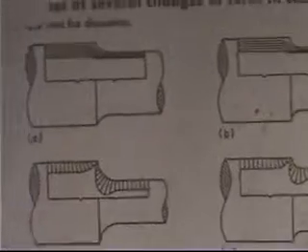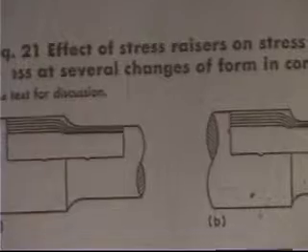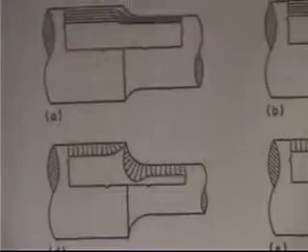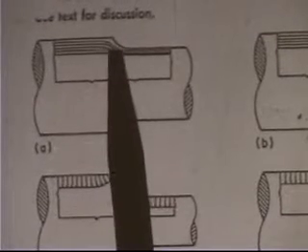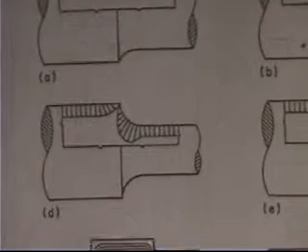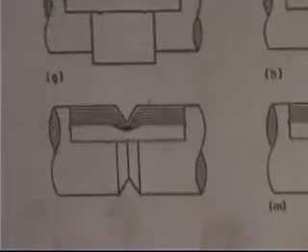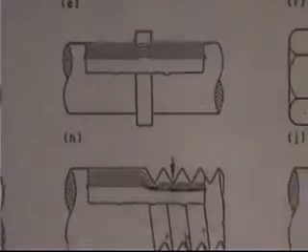If you really want to be precise, you can solve Laplace's equation for the stress. And it will show you that you'll get nice little contours, and wherever the lines congregate or tighten down, that's going to be a region of stress concentration. So you can have threads, you can have notches machined in, you can have fillets, you can have keyways in your part. So many times these things might be because of some keyway.